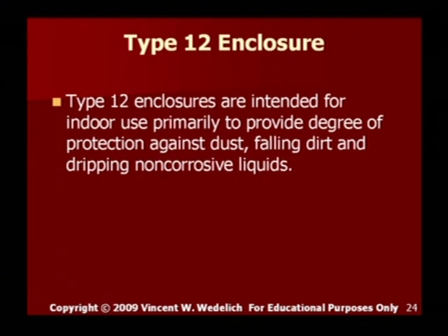Type 12 enclosures are really intended for indoor use as well, and they protect against dust, falling dirt, and dripping non-corrosive liquids. You see Type 12 enclosures in control rooms a lot where there's a dust problem and things like that. You'd think with a higher number, Type 12, that it would be a higher rating, but it's not the case. It's just dust proof.